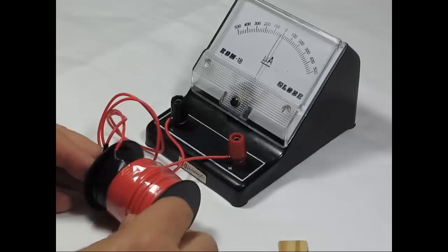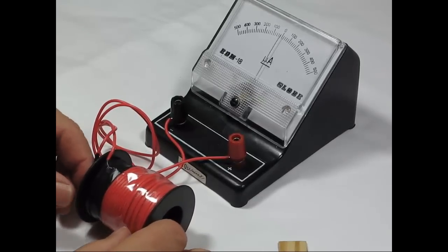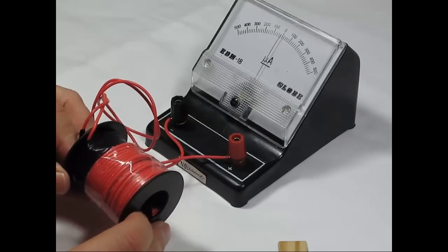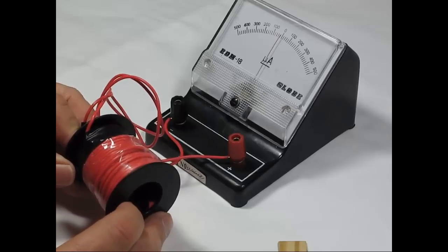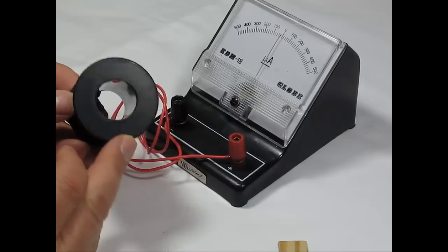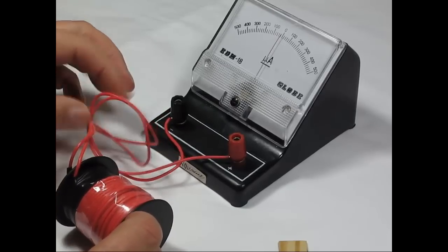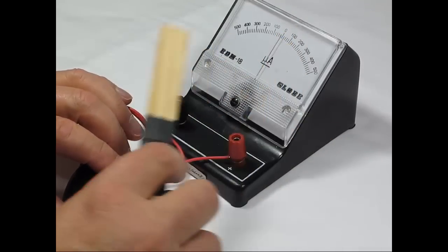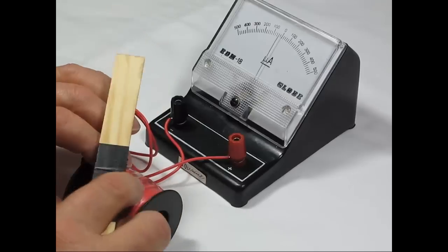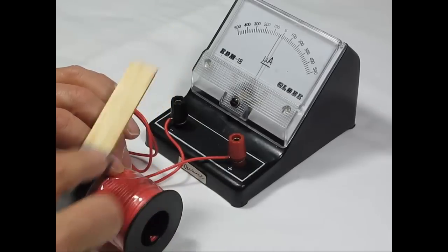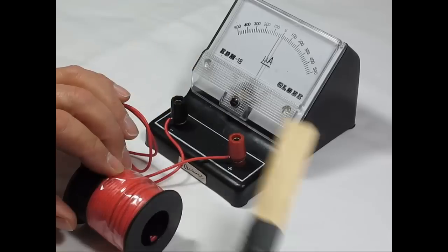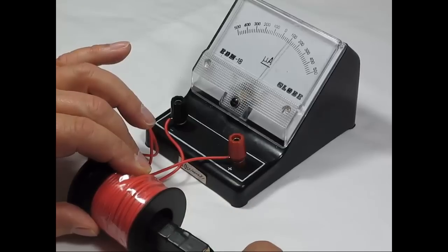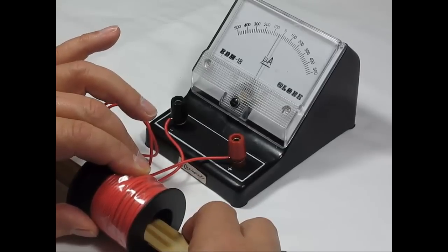What we have here is a coil of conductor, which is a partial spool of red 18 gauge conductor. Right on the spool it came on, I just pulled the ends off and hooked it up to the D'Arsonval meter movement. What you're going to do is watch this needle. Now you can see, just getting the magnet near this coil of wire, you can see some movement of the needle. Now I'm going to slide it inside. You can see that you can almost get the meter to peg.